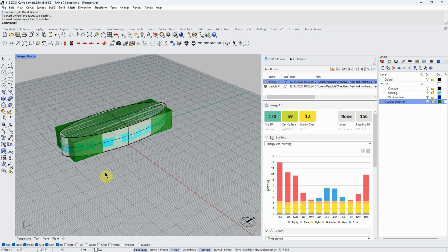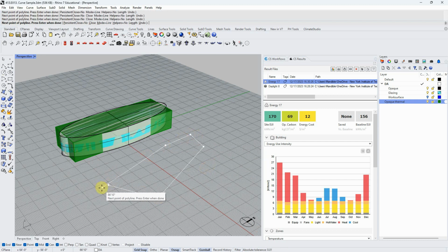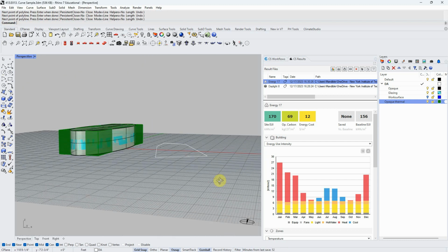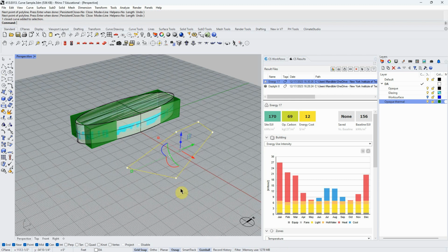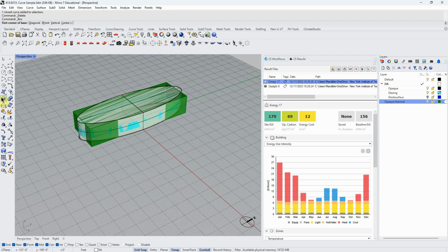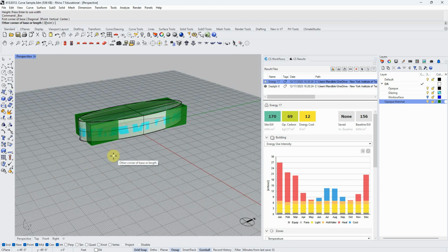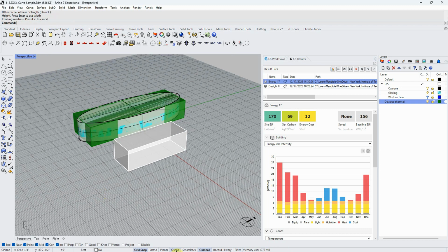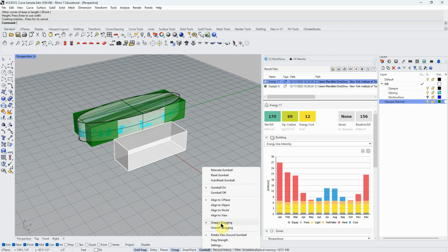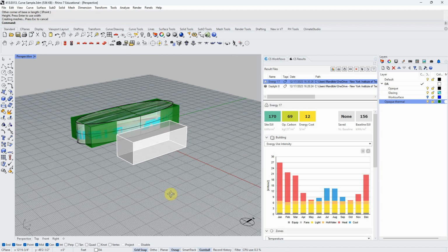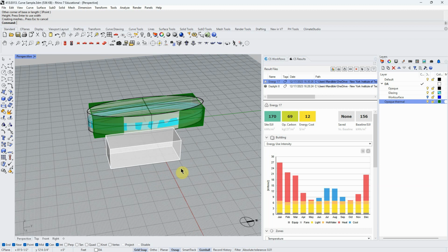So the way to solve that is definitely do not make a surface and then pull that up. Even if it's off just a little bit, that's going to mess you up. So I would use the box extrusion tool. Remember, if you keep your O snaps on and use your gumball snappy draggy setting, you can very quickly make these geometries relative to other things.